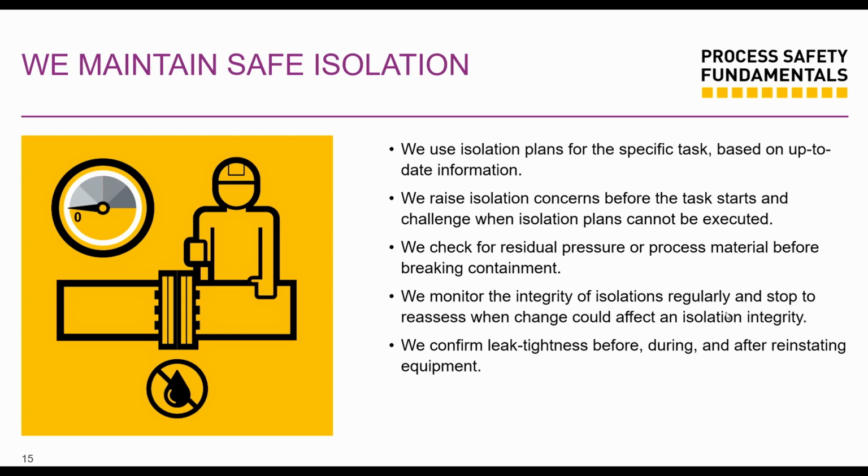So we'll want to also monitor the integrity of isolation. We should regularly stop and reassess if there's any change in our task that could affect our isolation integrity. Confirm leak tightness. We're testing visually. We're testing with gas detection before, during, and after reinstating equipment. You want to make sure that we are checking that we don't have any leaks.